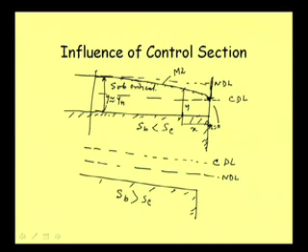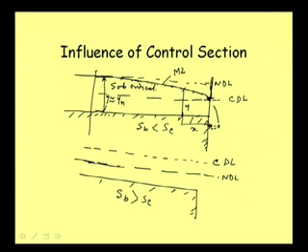Okay. Now, in nature, if we do not make any disturbance, then the flow depth will be coming along the normal depth line. So, it is coming like this, and at this point it will be falling like this. Now, as this is a supercritical flow, this flow will not be affected by the disturbance that is created at this section.